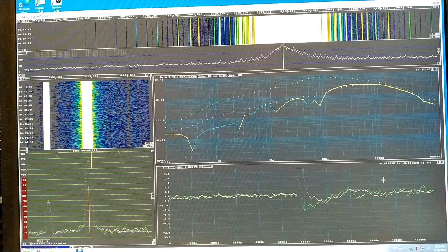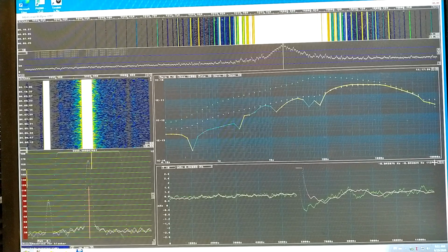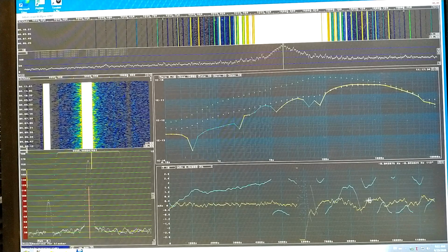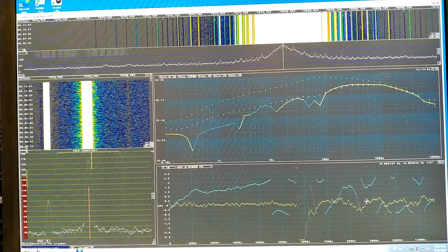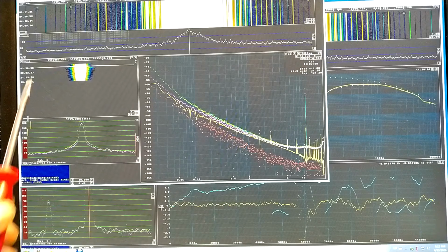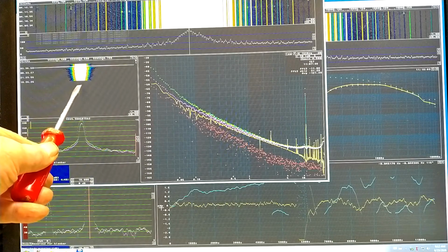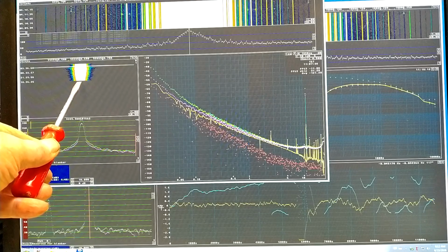Now I have 1.2 volts on the capacitance diodes. And I can see a clear difference here. It becomes more visible when I look at the frequency difference between the two channels. It's the yellow trace, and you can see it is very different. But the higher frequency noise that I can see here is clearly weaker. And one can see here, it is a little bit narrower, but it's not at all as good as it was when I started this measurement.